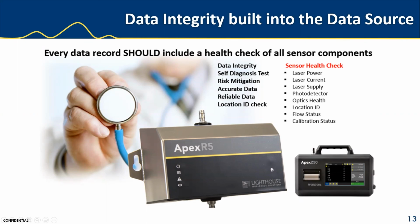So did you know that prior to this enhanced self-diagnostics, the #1 cause of failed calibrations was sensor contamination? How ironic that cleaning solution was the root cause. The sensor did not have the ability to detect that it had been contaminated, and that the contamination is enough to skew the count data and resize the particles incorrectly, then you're in for a lot of trouble. So there you have it. The source data is protected and validated as authentic.